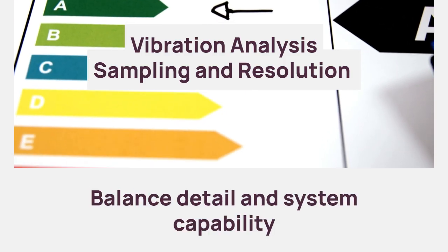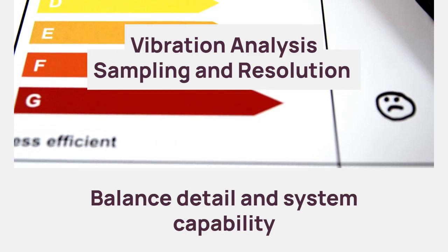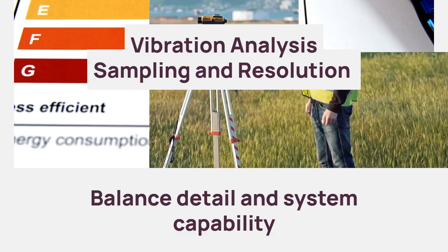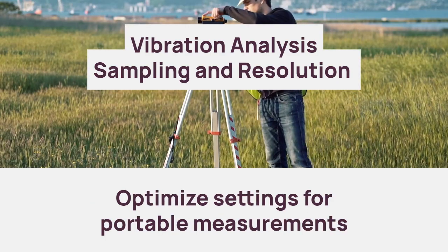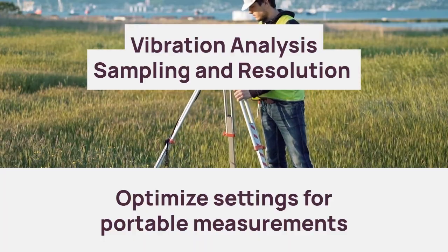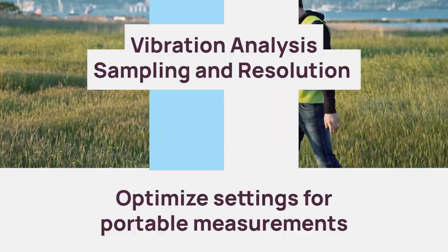But there's a balance. Higher sampling rates and more lines of resolution demand more memory and processing time. For portable route-based measurements, operators must optimize settings to maximize diagnostic value without overwhelming the system.